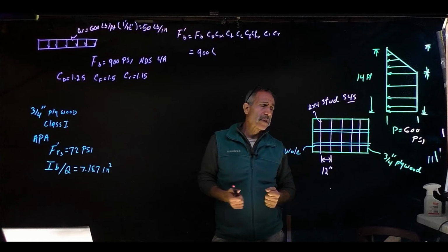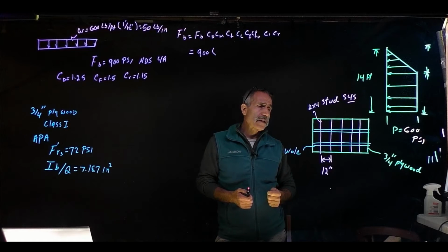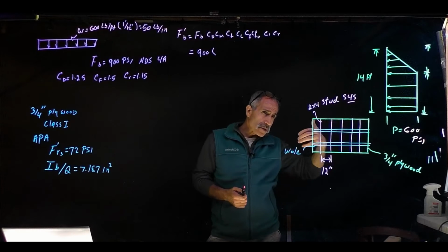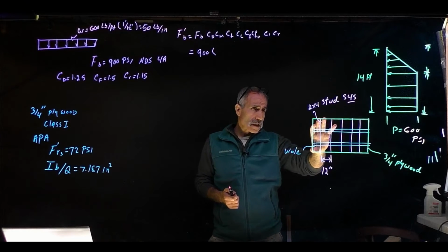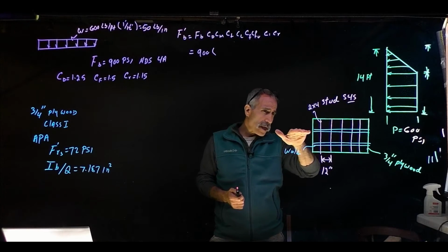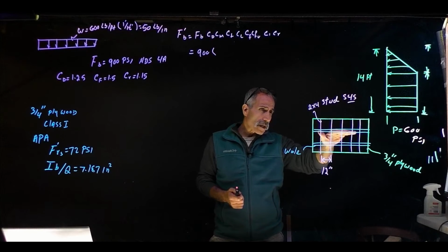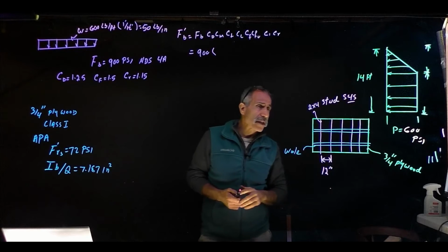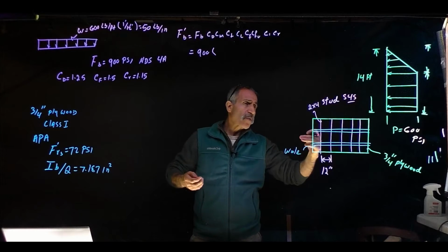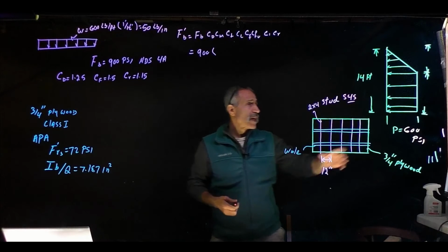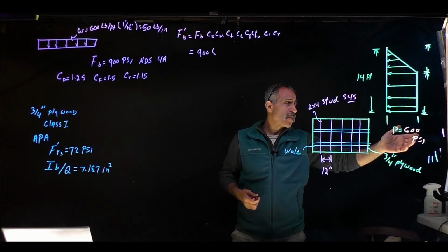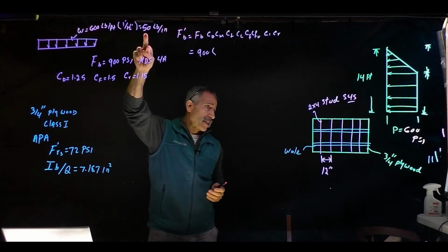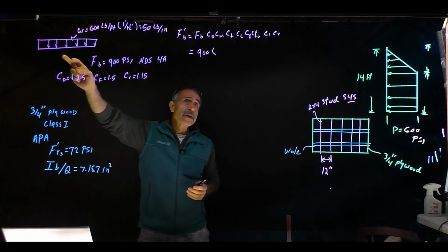All 4 criteria are going to be checked. You're looking at this, the pressure coming on the outside of this stud, and the stud is backed by this whaler, so this is a support system behind it. We can count that as a uniform distributed load, and our maximum is 600 pounds per square foot, or we can say it's the same as 50 pounds per inch on a beam.